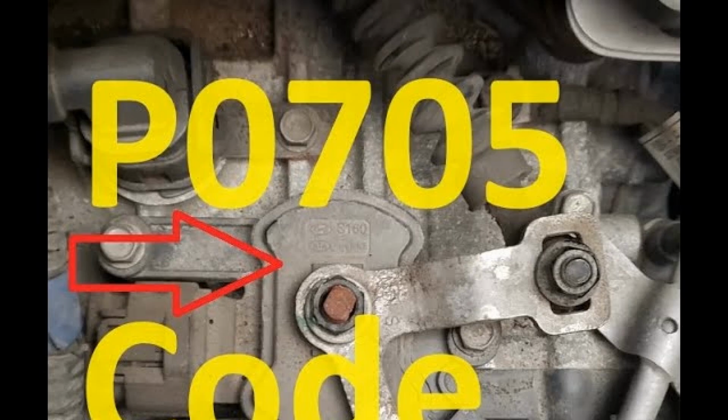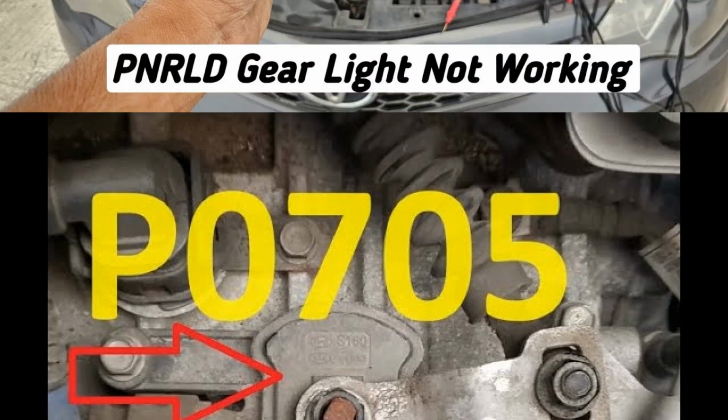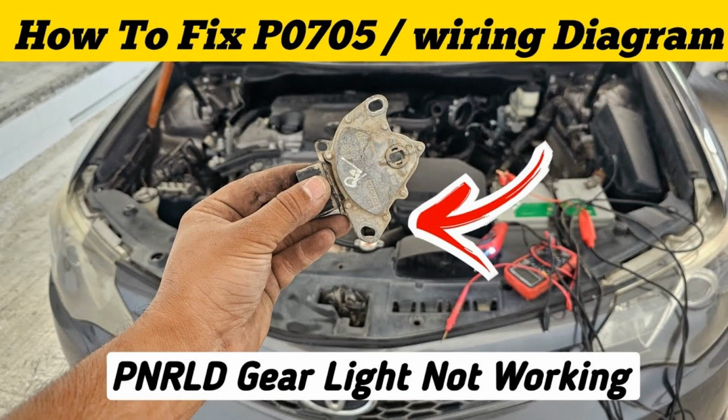The code informs you that the computer has detected a fault with the TR sensor. The sensor is either sending the wrong signal, or it is not sending any signal to the computer that detects the gear position. The control module receives signals from the vehicle's speed sensor as well as from the TR. When the vehicle is moving and the computer receives conflicting signals, for example, the TR signal indicates that the vehicle is parked. However, the speed sensor indicates that it is moving. Code P0705 is set.